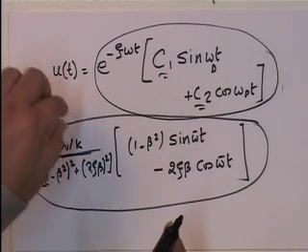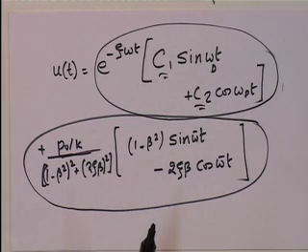So, that gives you the static response, but the dynamic part depends on two terms. One term is xi, which is the damping ratio, and the other important parameter is beta. Beta is the frequency ratio. It is the ratio of the excitation frequency to the natural frequency of the structure.